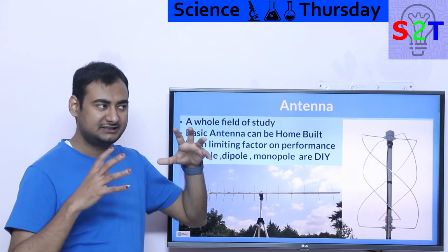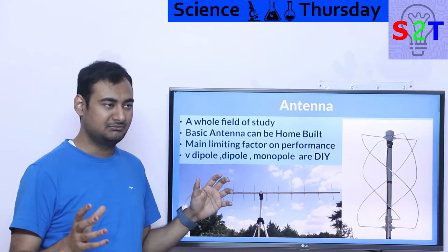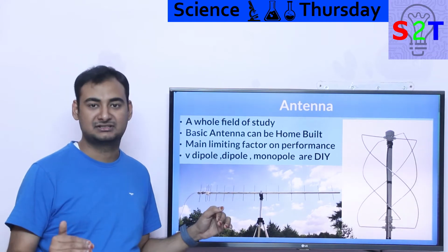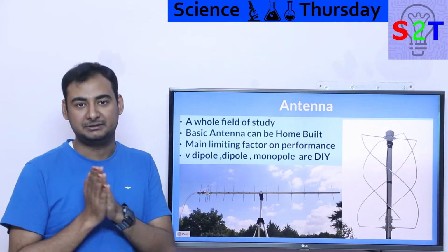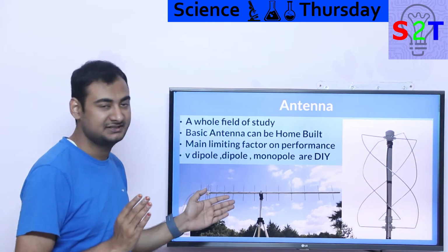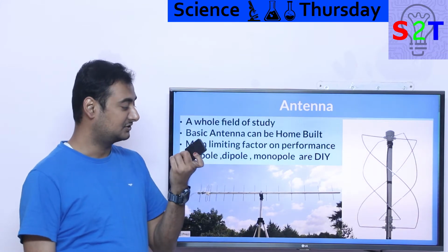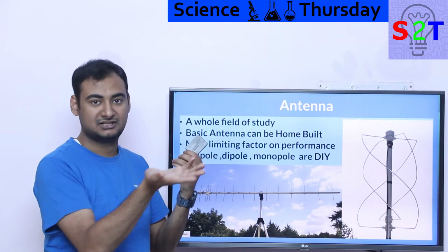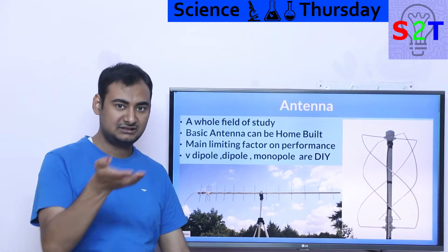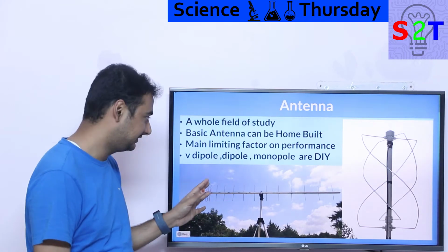because it's almost like how a camera works. You can have the most amazing camera, the most amazing sensor, 60 megapixel, an amazing stacked sensor, but if you have a crappy lens, you're going to get poor results out of it. Same happens here. If you have a good radio receiver, a good SDR, let's say an Airspy Discovery, but the signal coming into it is garbage, it is going to spit out garbage. It's like how computers are: garbage in, garbage out. So you have to understand this is the main limiting factor of your system.